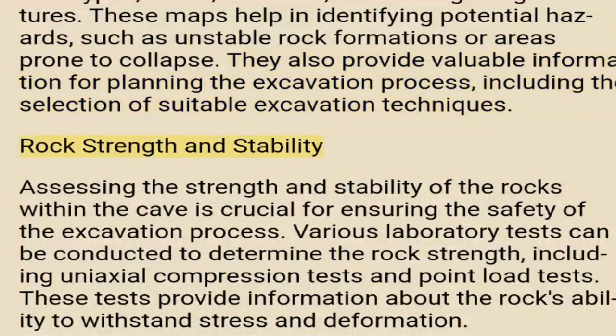Rock strength and stability. Assessing the strength and stability of the rocks within the cave is crucial for ensuring the safety of the excavation process. Various laboratory tests can be conducted to determine the rock strength, including uniaxial compression tests and point load tests. These tests provide information about the rock's ability to withstand stress and deformation.